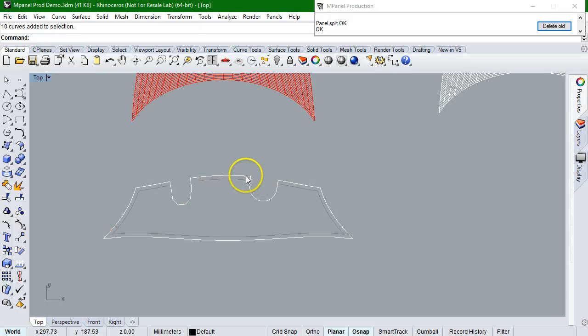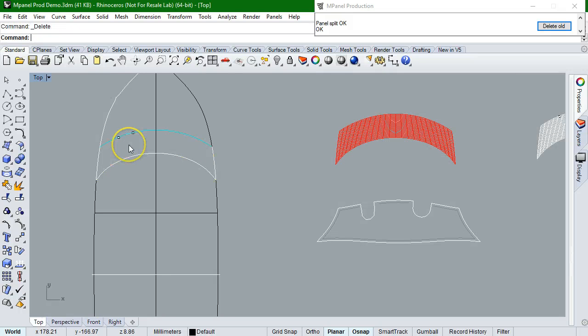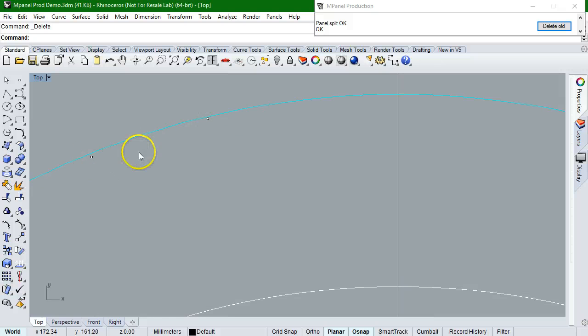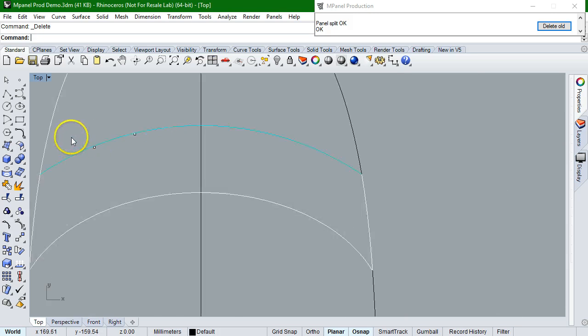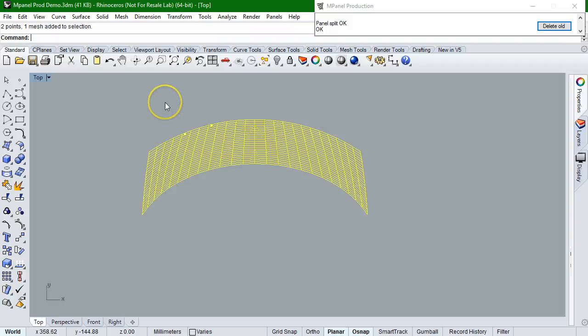Now often the position of the cutout needs to be determined from information that has been machine measured, and we would typically have that, get rid of that mesh, in the original frame measurement as a couple of points, and these are Rhino points, just ordinary 3D points. If your measuring equipment doesn't produce points, or can't be set to produce points for these locations, you might have to have a polyline drawn across there, and you might have to put a point on the end of the polyline to get to that. Once we have those points of course in the paneling, so I'll just go ahead and panel that.